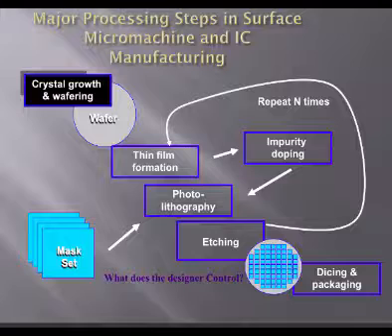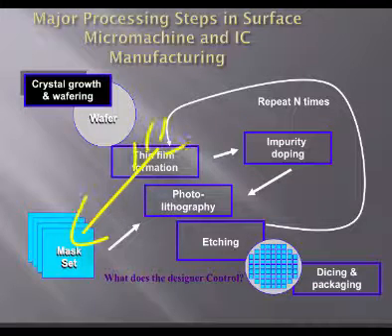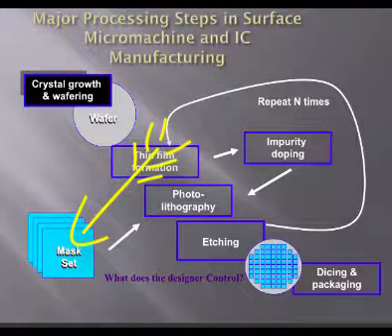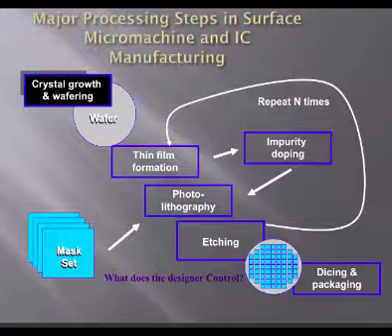Mask set, maybe? Yeah. He makes the masks. That's what the designer does. So he makes the designs, he makes the masks, and then sends his design to a mask shop. They make photo masks. They take his design, they put it on chrome and glass, usually. Right? If it's LIGA, it's what? Gold and beryllium. But they'll make chrome and glass sets, and there's a set for each layer, each design layer.